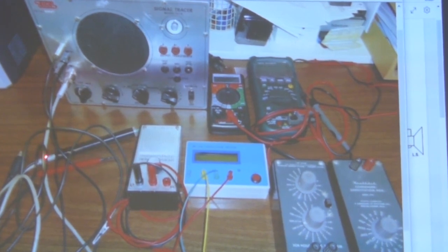So you want to have a high voltage capacitor, maybe a 0.01 of 400 volts or so, and you can rejig this thing in order to make it work for both types of radios, transistorized or vacuum tube. Okay, and here's an ordinary digital multimeter, which is what you absolutely need if you're going to be in this business. Here's a more expensive one that also has a capacitance reading function on it.